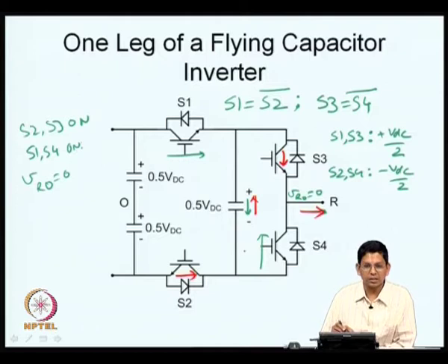And you see that this capacitor, its terminals are not connected to any firm potential, whereas this capacitor's terminals are connected to firm potential. These two are actually connected to some DC supply. So, they are connected to firm potentials, and this is just a series connection of capacitors now. And if you look at here, neither of these two terminals are connected to any firm potentials, they are actually connected to switches now. Therefore, you get the name flying capacitor. Basically, the capacitor's terminals are not connected to firm potentials, it is floating, or it is a flying capacitor inverter now.